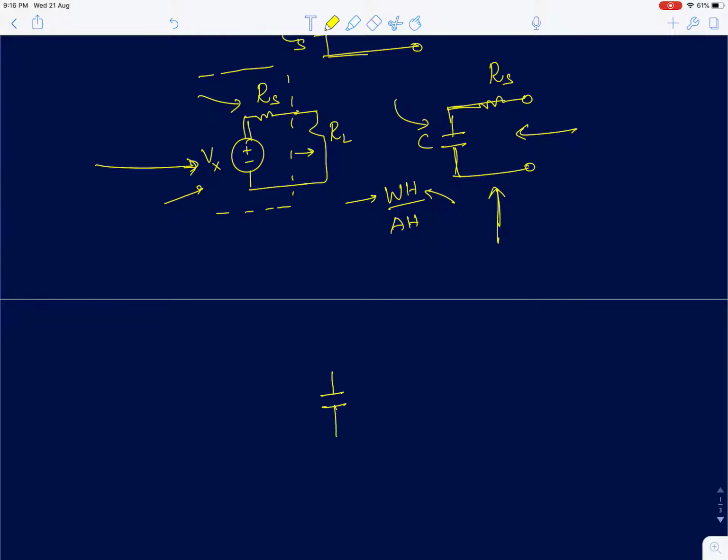Also, practical capacitors come with finite series resistance when we use them in oscillators, digitally controlled oscillators in RF circuits, radio frequency circuits. Even in those applications, one is interested in knowing the effect of the series resistance on the overall capacitor behavior. How does it change by adding the series resistance, and how can you quantify how good a capacitor is?